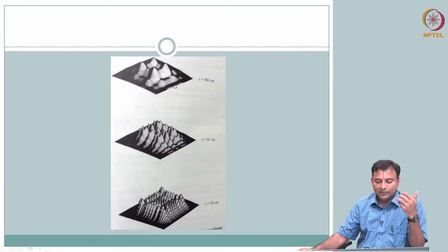So, what we will do is we will just quickly show some. This is from a rectangular transducer, what I showed before was circular, this is rectangular, and you see the similar trend in the near field. What is a near field or far field? Remember, go back, we just made some formulations, right? If it's a circular disc, d square by 4 lambda, so 2 times that, so d square by 2 lambda.